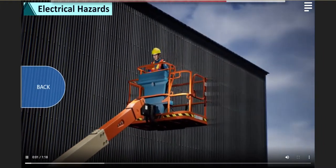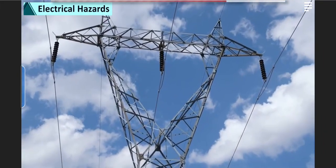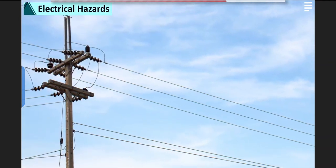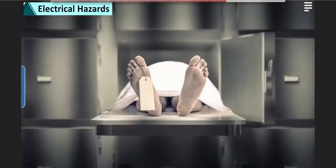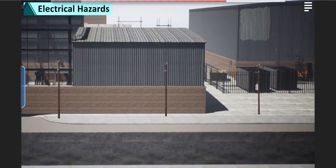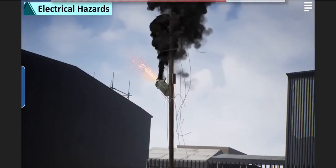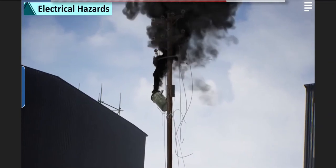While operating or occupying a MEWP, you must be aware of power lines and other electrical hazards nearby. Touching energized power lines can kill a person instantly. Even if you don't touch the lines, you can still be injured or killed by an arc flash, which is a sudden explosion caused by electricity traveling through the air.